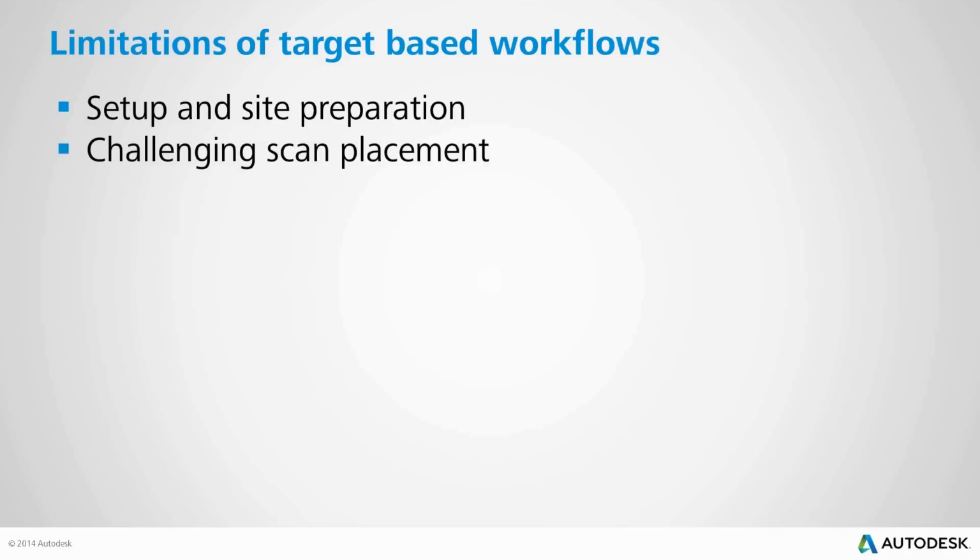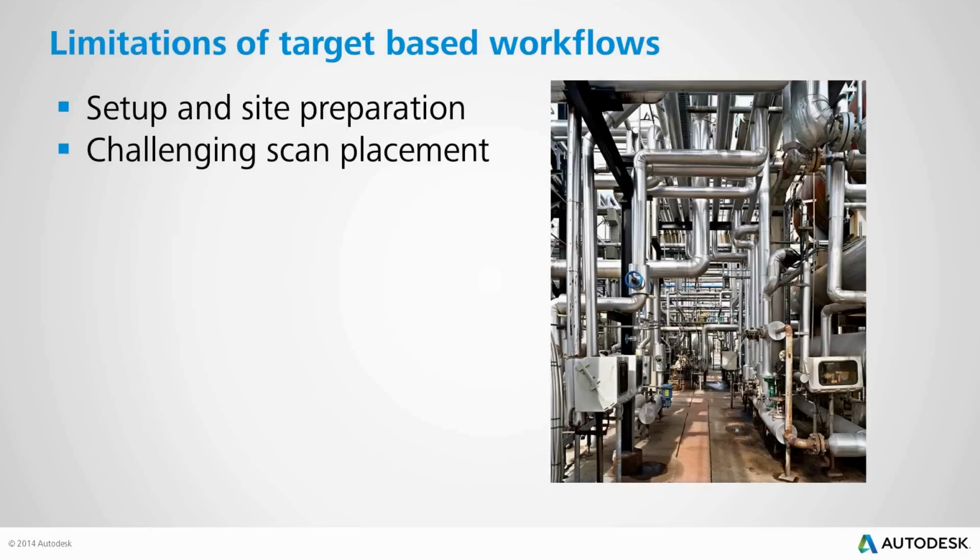Scan placement can be a challenge. In the example I showed earlier with an office space, no matter where you are in the office, you can usually see quite a few targets. But how about an environment like this? First of all, it's difficult to find places to put targets, but it's even more difficult to find scan locations where you can see all those targets. So definitely a lot of headaches for field crews in these types of environments.